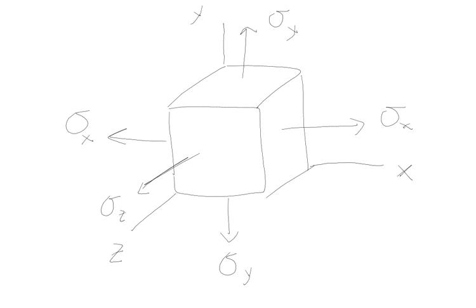What if I go ahead and try to shear it? Like if I try to push that top surface towards the right, and then I try to push the bottom surface towards the left. That gives me a shear. That's basically trying to rip this cube apart, okay? So I could have a shear stress now in that direction. Likewise, I could try to shear this top surface towards the front, I could try to shear this surface up, I could try to shear it to the right. I can try to shear this up, shear this left.